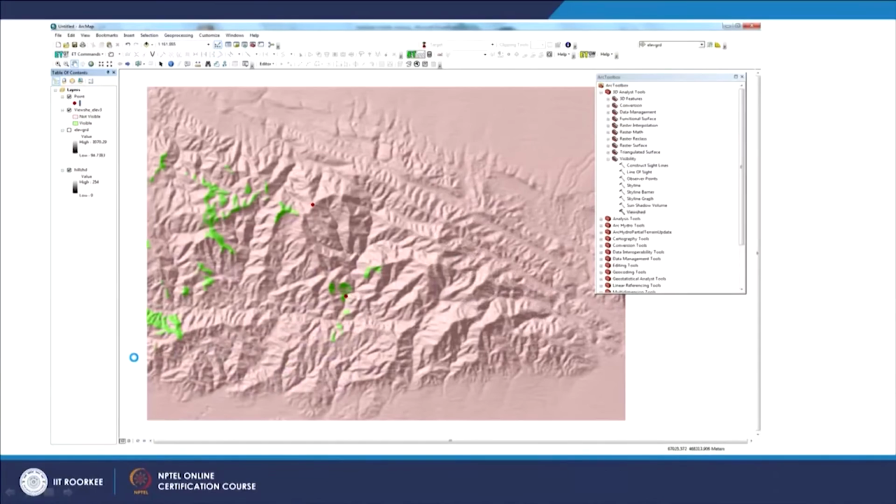Like here, this is the screenshot of ArcGIS analysis. The person offset is given here, the person is standing here, or a tower. Now from here we would like to know, and also one more here, for this area the analysis has been done. It is not necessary that the entire circular area should be covered; we can restrict it to a particular angle or arc I want to analyze. So, all green areas are visible and all other areas are not visible.